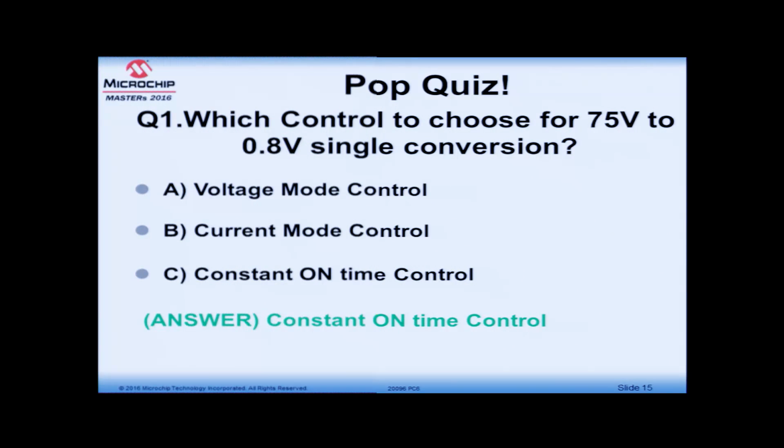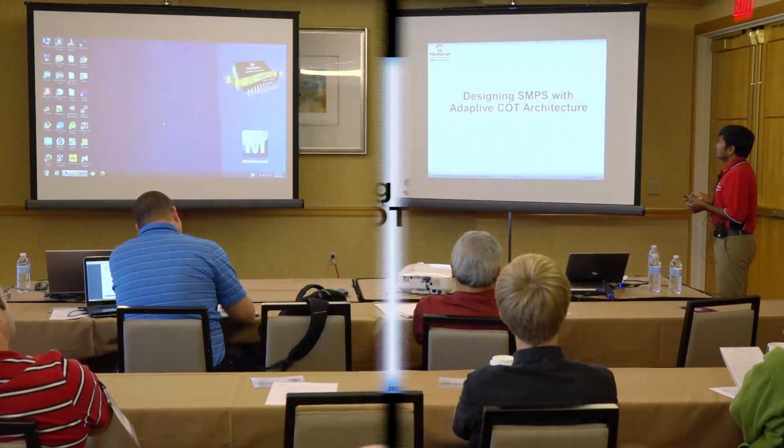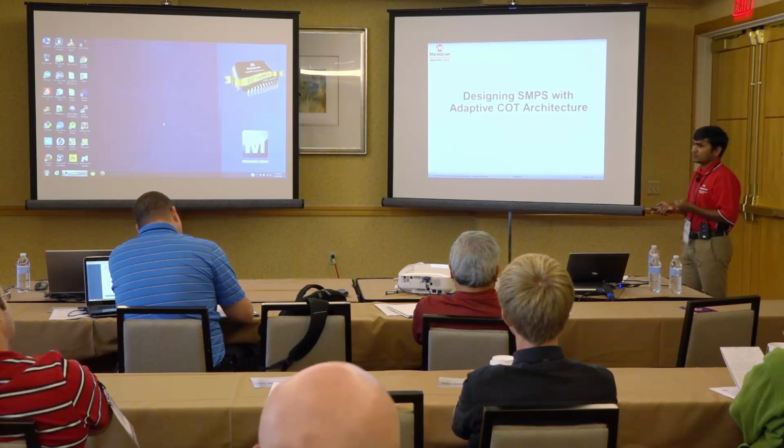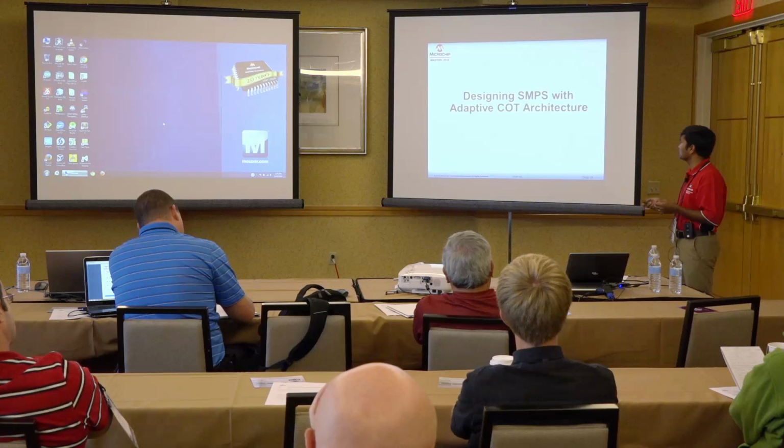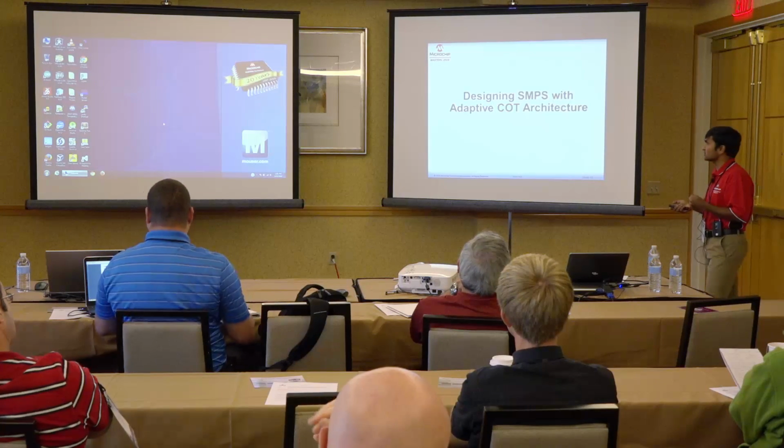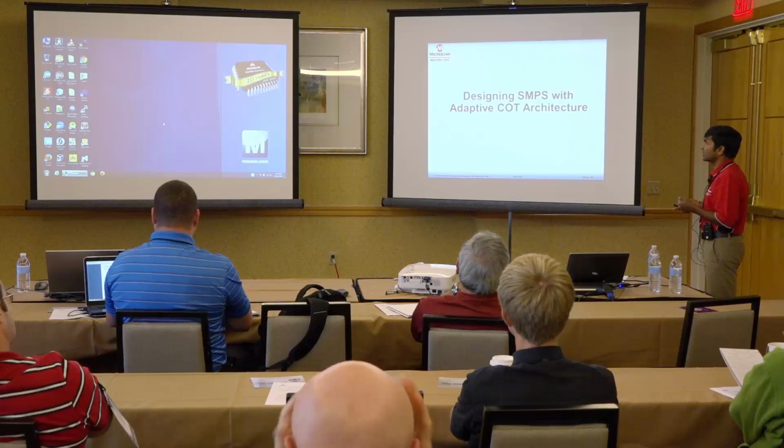In a lot of our data sheets, you can see the efficiency curves also given for this 75 volts to 0.8 volt. Okay, so now we understood the adaptive COT architecture. Let us work on the design, how we can design an SMPS with adaptive COT architecture.